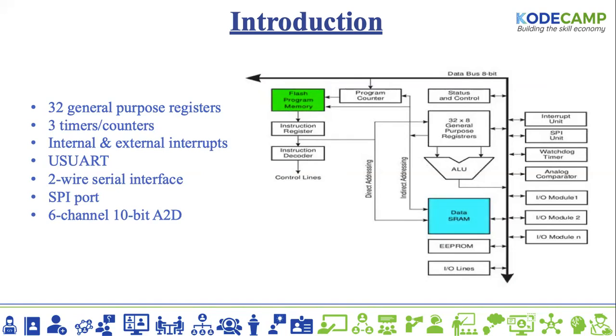Some of those ports can be bidirectional. When I talk about bidirectional, it can be an input or an output. Examples of such pins are pin number 3, pin number 9, pin number 10, pin number 11. They can be used for analog input and also for digital input, and for analog output as well, so both digital and analog input and output. In summary, that's the port features.